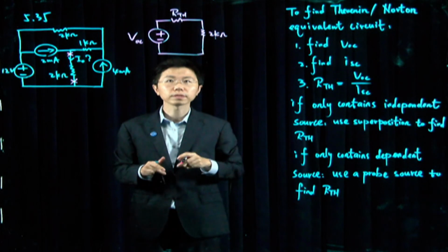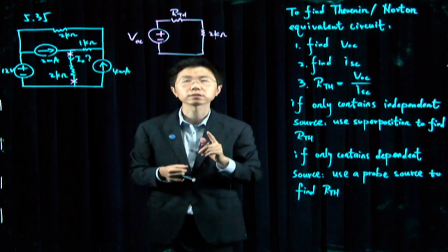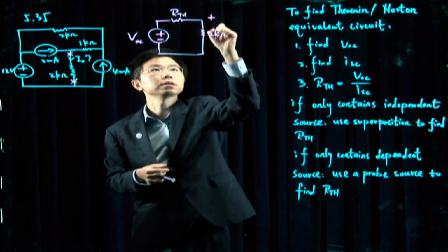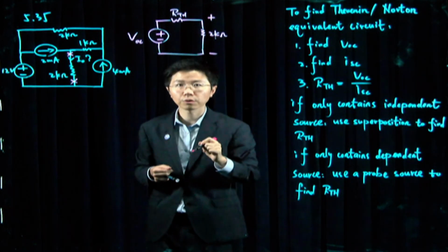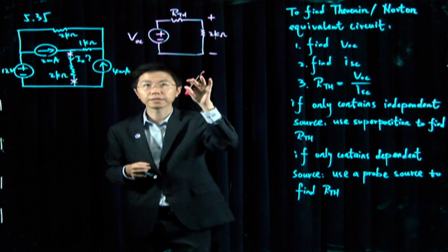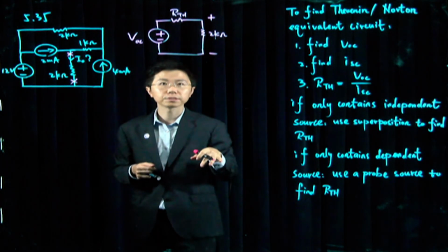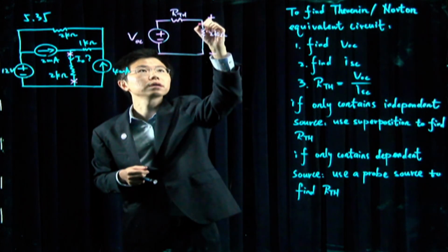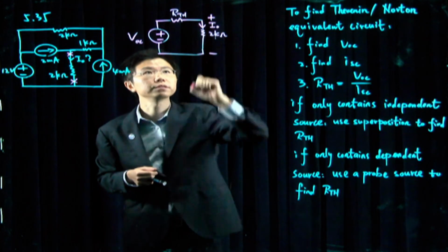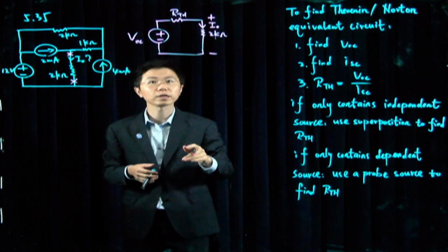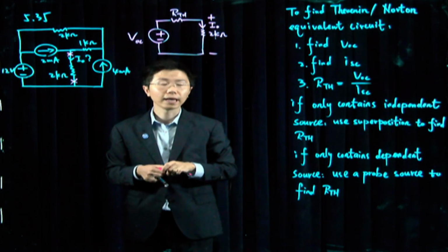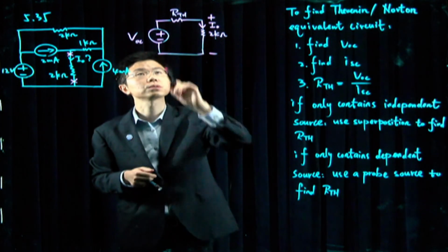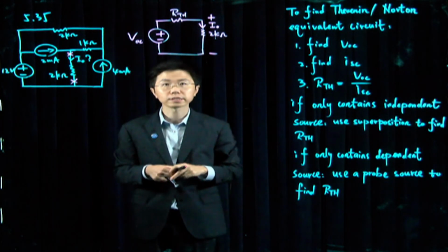One thing to note is that there are reference directions for the equivalent circuits. If you draw your equivalent circuit this way, the top is the positive terminal and the bottom is the negative terminal. Since I0 follows our passive sign convention, it's convenient to write it this way. Our next step is to find VOC and RTH for the Thevenin equivalent circuit.